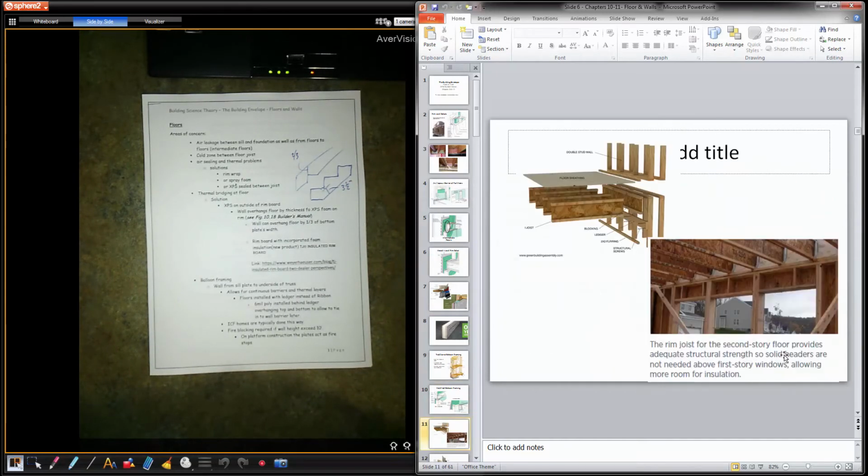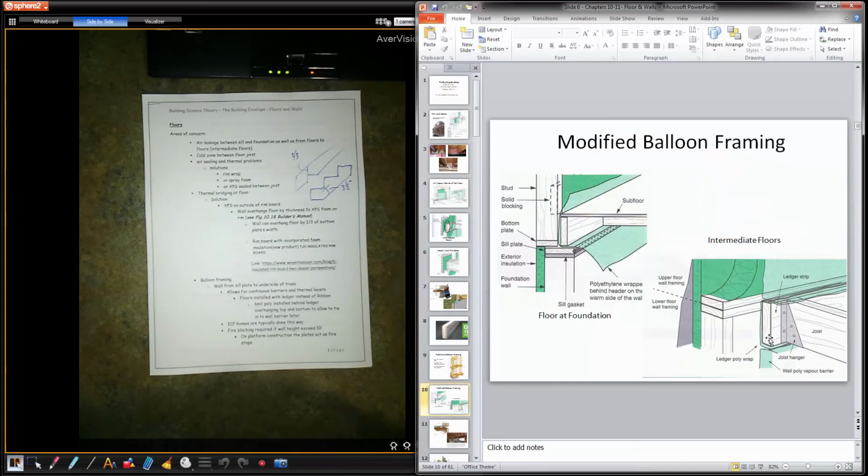Or you'll have to put joist hangers. Right? So if you're not bearing enough, see here, that's probably 1.5 inches. You see this looks like 1.5 inches, so that looks like the same, maybe a little bit bigger. So that's fine, that'll work. You just got to keep that in mind.